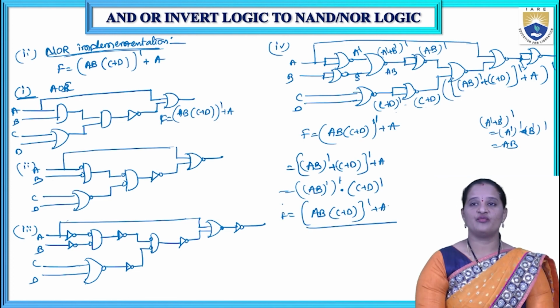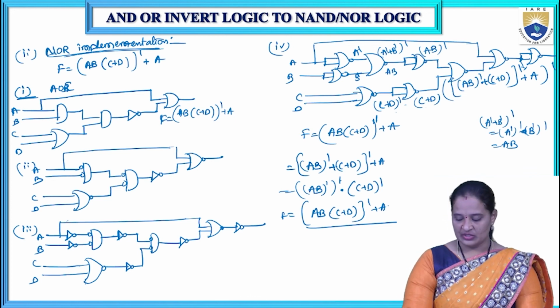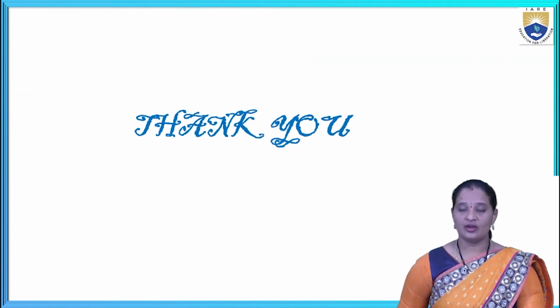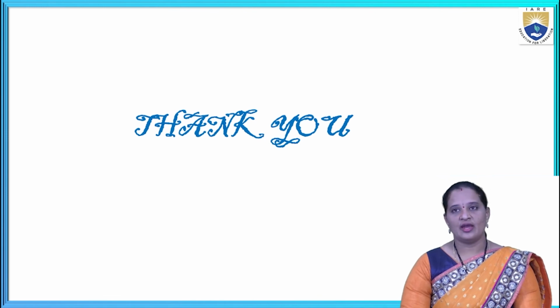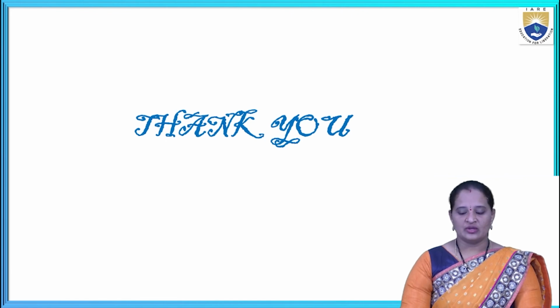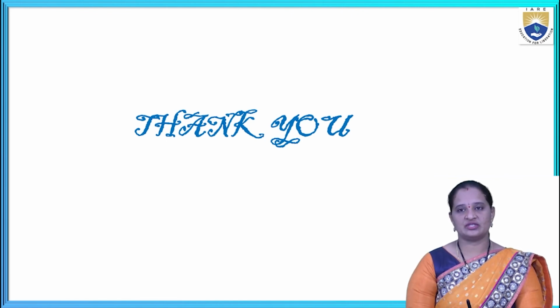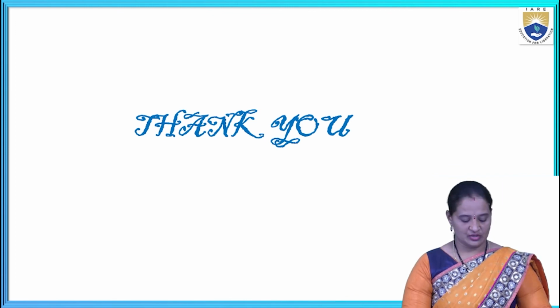So this is how we can realize any Boolean expression using NAND or NOR logic. As the NAND and NOR gates are universal logic gates, any logic can be implemented using NAND and NOR. And the only thing is we need to remember the conversion procedure from AOI logic into NAND or NOR logic. So by using that procedure, you can convert any complex logic into NAND implementation or NOR implementation. So that's all for this lecture. I hope it is clear to you all.